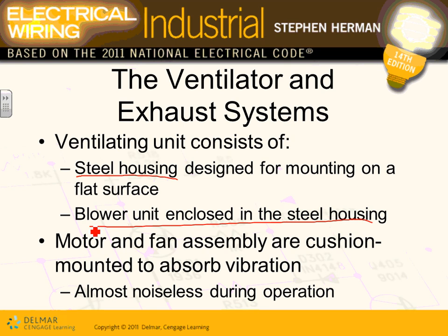That's none of our business, basically. That's a mechanical engineer's business, Adam. Our business is to coordinate with our fellow mechanical engineers and tell them where do you want your exhaust fans. They put them in certain locations, give us the horsepower and the voltage, and we go size the feeder that goes to it. There's vibration absorption, and all of this is done by the mechanical guys. It comes as a set, guys. The mechanical contractor will sit it on a roof. The electrical contractor comes and puts the electrical feeder into it.